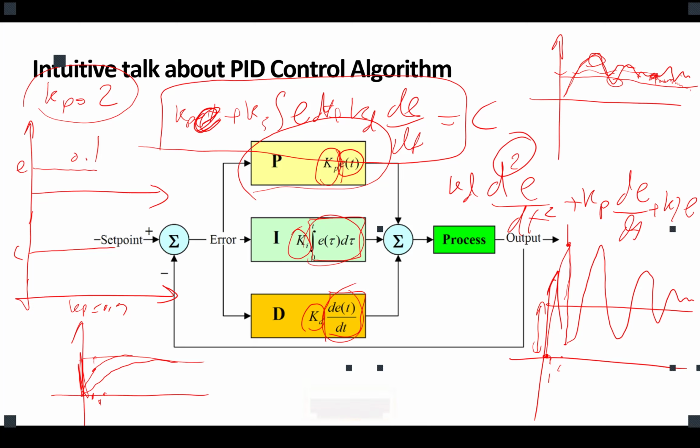Yeah, go. Are the gains for each PID independent of each other, or are those the same value? No, independent. When we talk about the PLC or those standalone controllers, they are basically digital electronic systems. So you actually set the values, so they are independent. If you wanted to drive the analog system controller, we already talked about that.